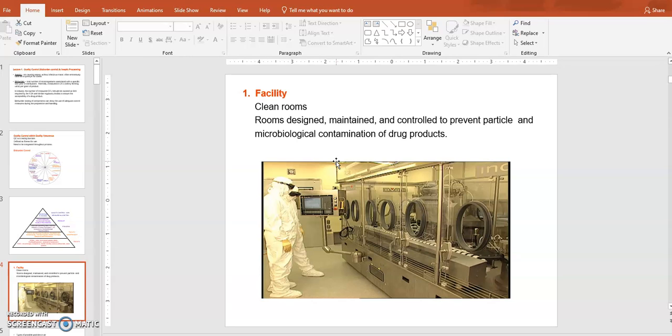Okay, so when you say clean room, what does that mean? A room should be clean. Of course, it's not just that, it's a very controlled space. That's what a clean room is, right? From the beginning of the room design, you have to consider that the space should be all sealed up, and only controlled airflow will be admitted. And when people and materials are brought in, they should do that through controlled entries.